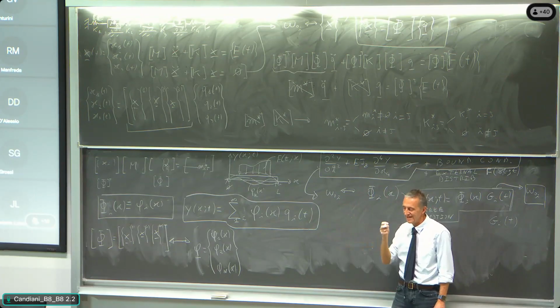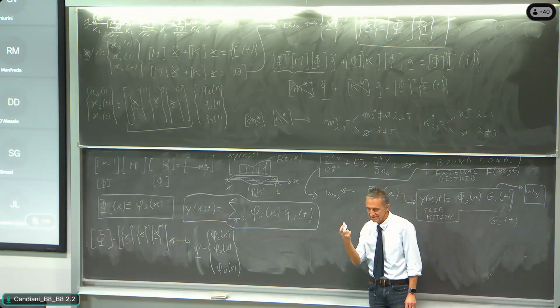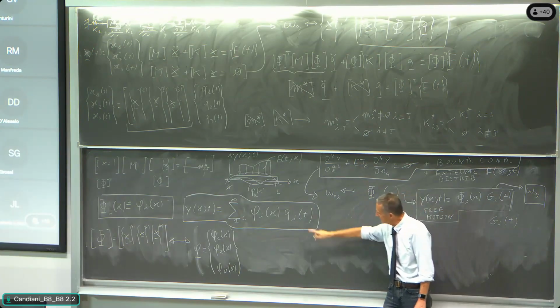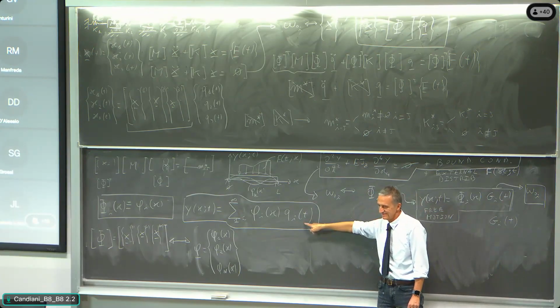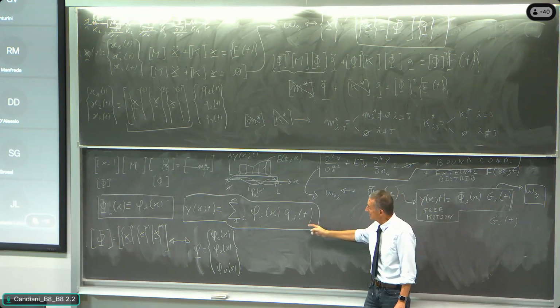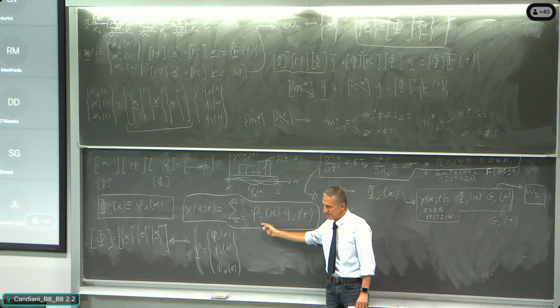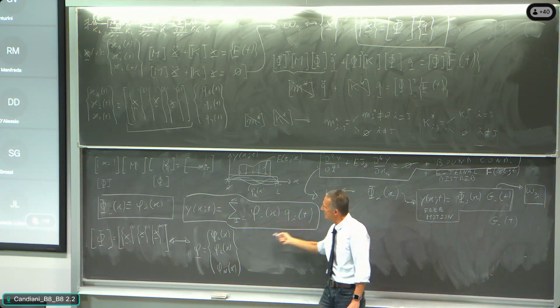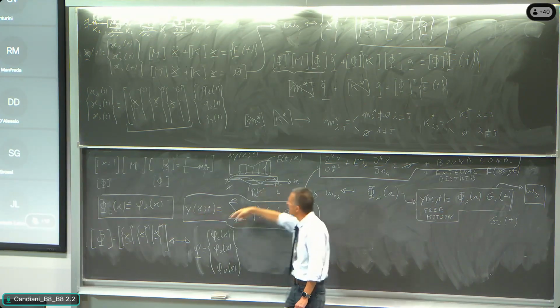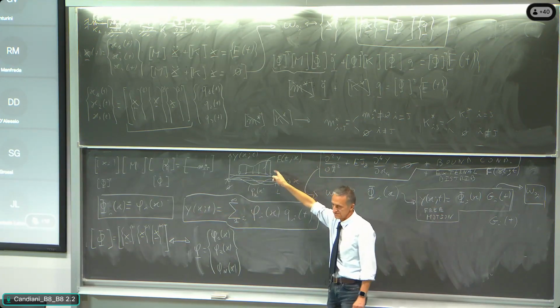So the unknown of the problem, that is the object of the study of the dynamics, is the function Qi function of time, that multiplied by the modal shapes are giving the representation of the way in which the system is moving as an effect of the excitation.